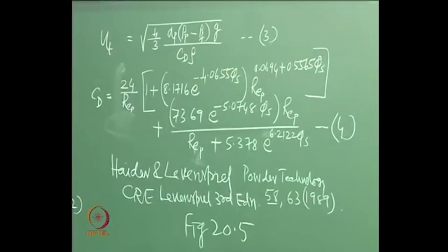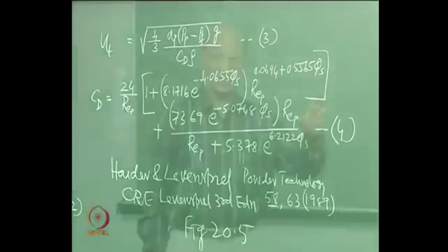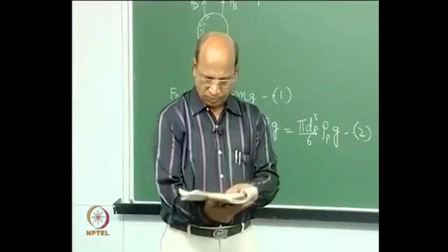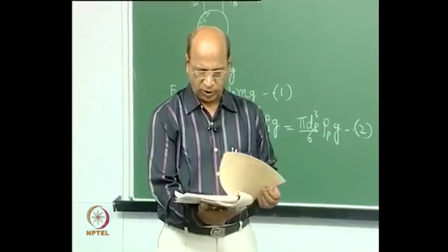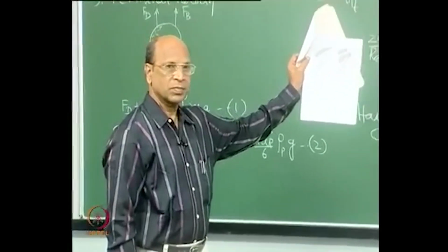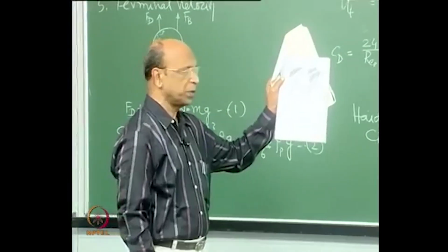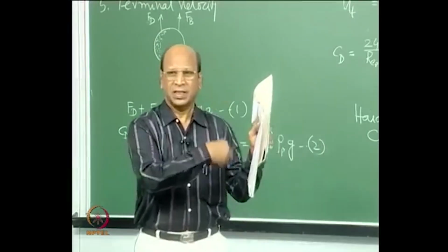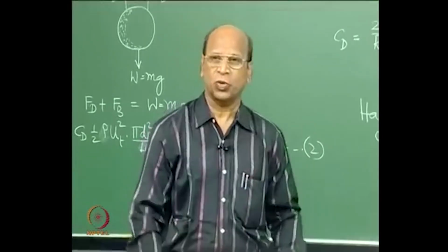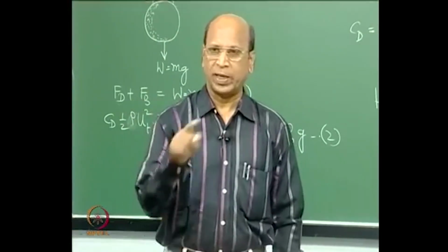This figure gives one dimensionless number, equivalent to the Archimedes number, versus UMF and UT, and there are many other things also in that graph. I have brought that graph here to show you, because you would never have seen it. If you know the x axis, dp star, he has used some other dimensionless number, so that will be the Archimedes number: g dp cubed, rho f, rho s minus rho f, by mu squared.